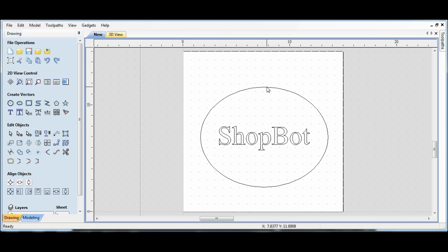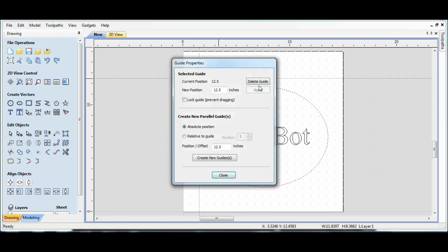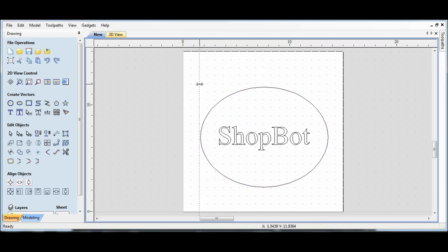Select mode, that's all that does. You can't do anything. I can't rotate, scale, or move it. It just allows you to select things. So if you need to move, have some guide rulers. These guide rulers, you can't turn those into toolpaths. Those are invisible once you get your toolpath selection. Those are there just to help you line things up and make things proportional and things like that. If you need to get rid of them, just right-click and press delete or select delete.